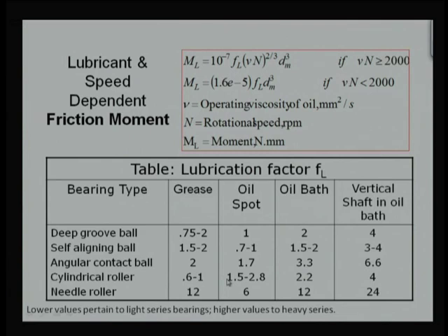Now, if we consider friction also as one of the objective functions, then in some cases angular contact ball bearing is going to give a better result, and in some cases the deep groove ball bearing is going to give better results. So it will depend on the main aim of that bearing. Is it more support or lesser friction? Whichever is more dominating, we choose a bearing accordingly.